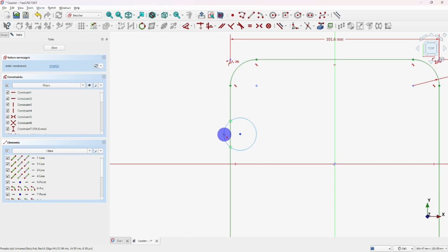It shows you the intersections with little green circles. It's going to trim from circle to circle, and if we selected it over on the right side, it would take that piece out. But we want to take this piece, do that, and then we'll see what effect that has. Right click to get out of that.